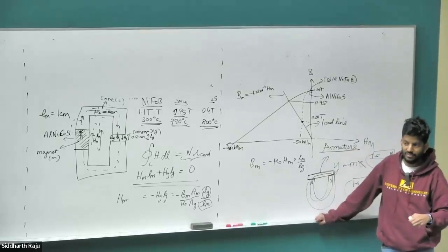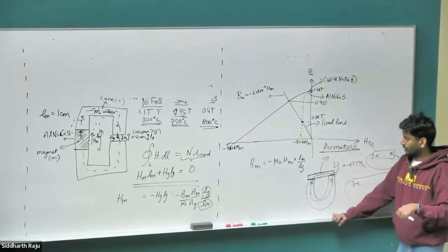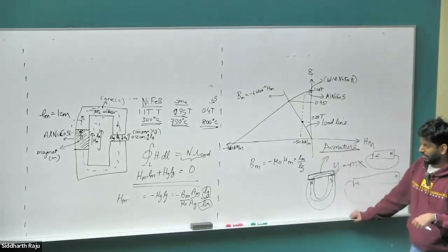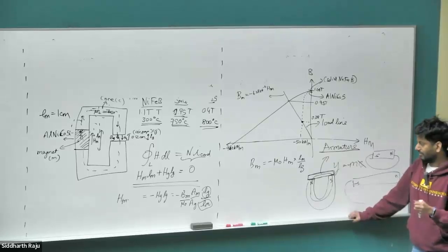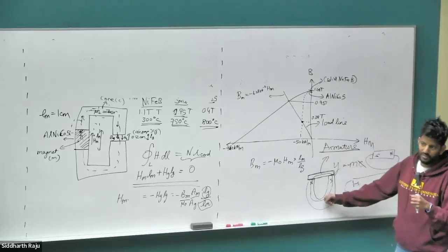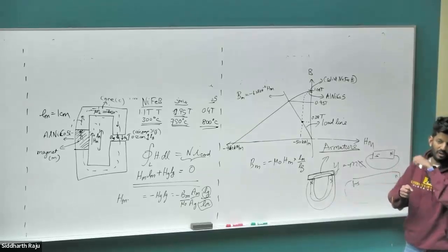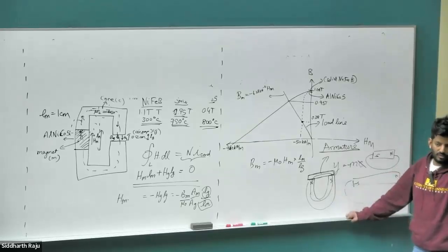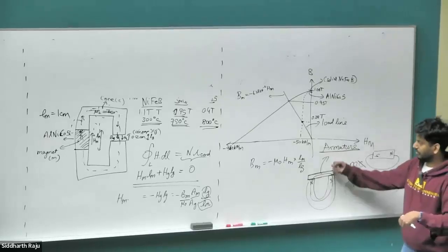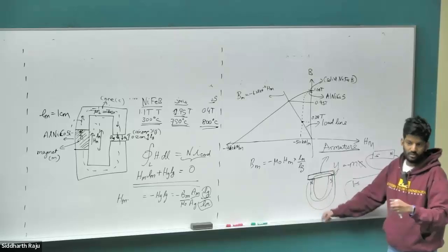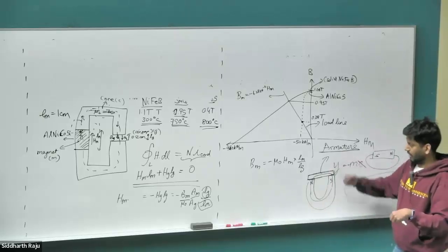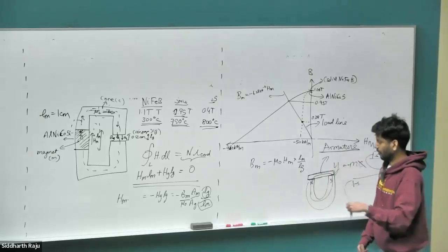Where? Motors. Rotor. So in a DC motor, we call the rotor the armature because in the DC motor, the stator magnets, in many cases, would be Alnico magnets. And if the rotor is not present, then there will be a large air gap between the two magnets, one on the left and one on the right, that will demagnetize it. So the rotor plays the role of an armature plate, with the magnetic pathway being reduced because of the rotor structure. That's where the name armature comes from in a DC motor too.